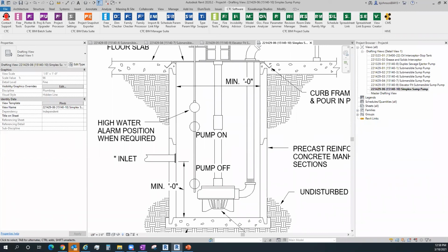Data size display, helping keep details to a minimal size. Number of lines is going to be your basis of how large the detail is realistically. So if I explode everything out and I've got 15,000 tiny little lines, my detail when it imports is 2 megabytes versus a half a megabyte on a regular one.